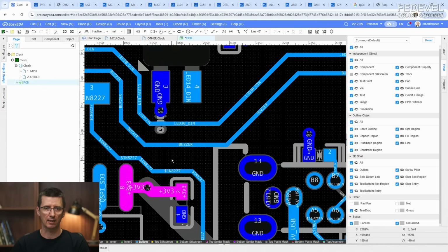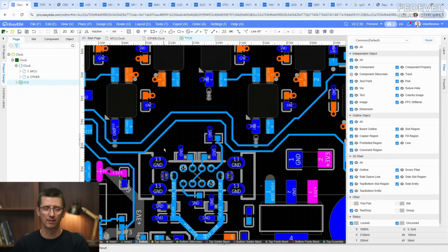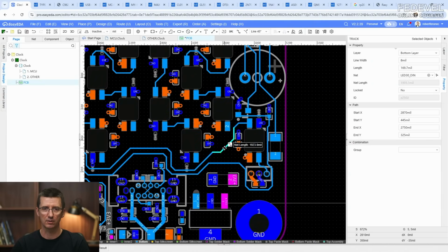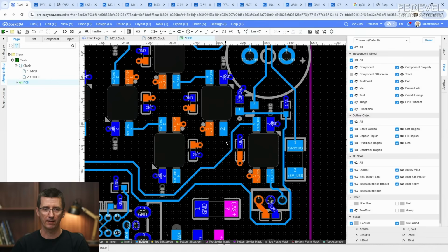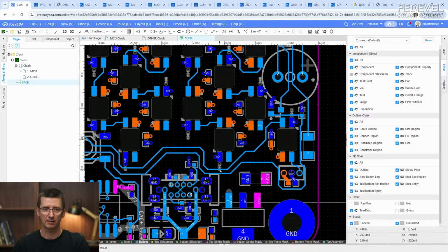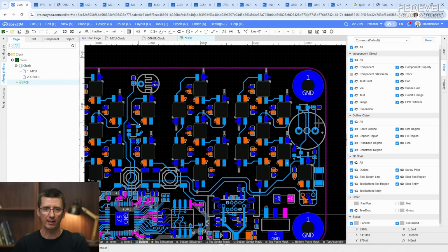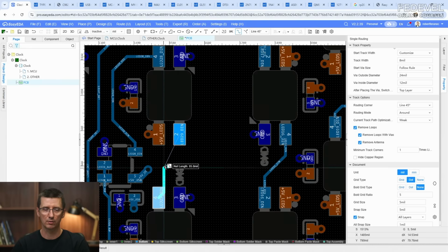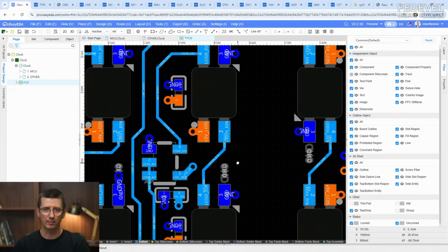Because, you know, a signal traveling through one track, if the tracks are routed very close to each other, can create noise on the track which is routed very close. If we spread the tracks, if there is a big distance between them, then the noise will be much lower, or there will be no noise picked up by the neighbor tracks.